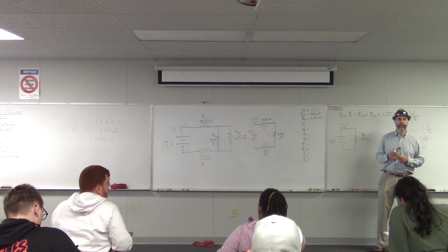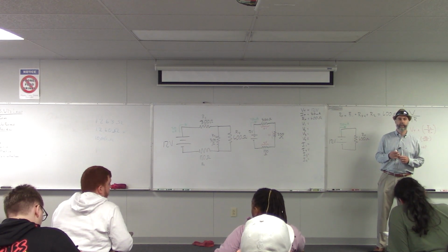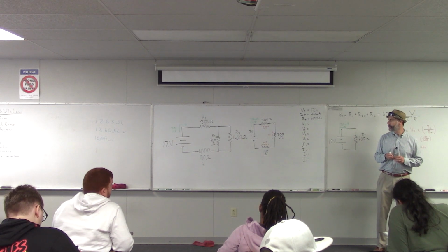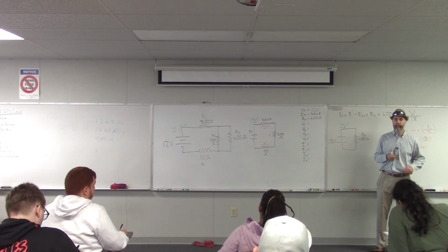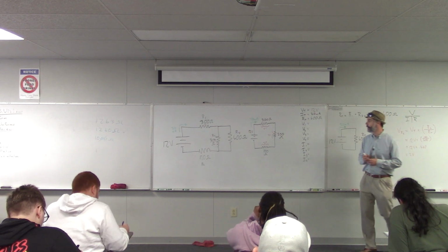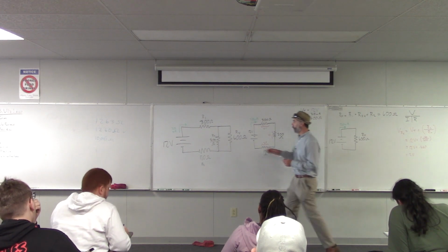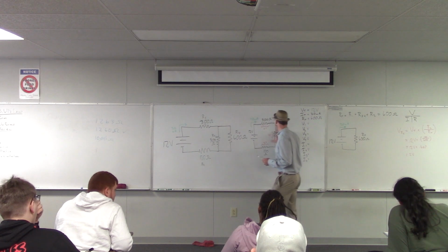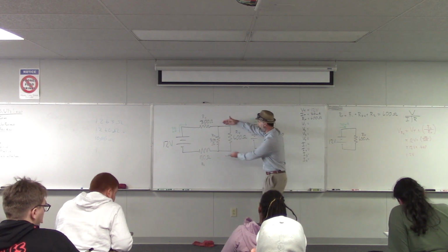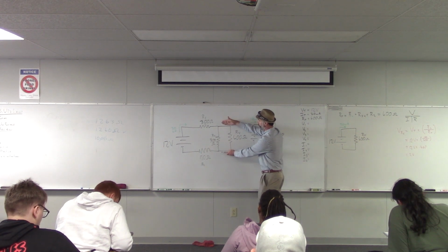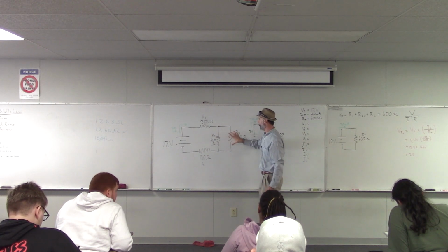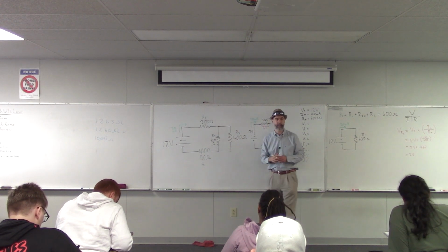There'd be no difference if they had different resistance between those two? R3 and R4 being different ohms doesn't change the voltage for both of them being 4 volts? Correct. R3 and R4 both have 4 volts across them because they are in parallel. And in parallel circuits, the voltages are always the same across the elements.